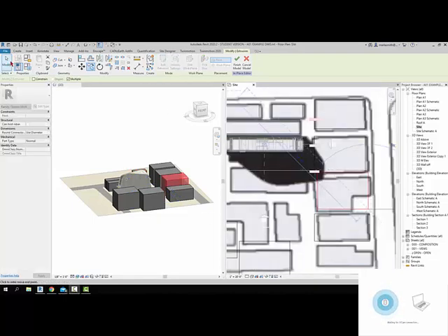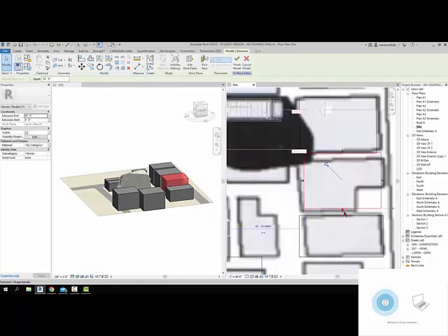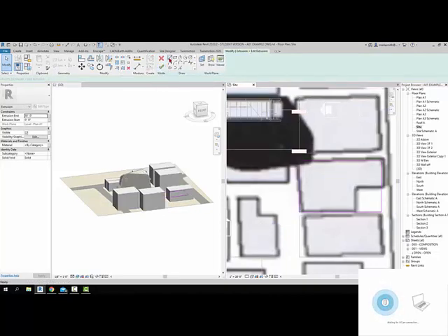I did want to show you this. There's one that has a jog in it, so I have this one in place to be that one. If I move it to where it would be close, I can select that and edit the extrusion, and just draw lines that make this into that shape.